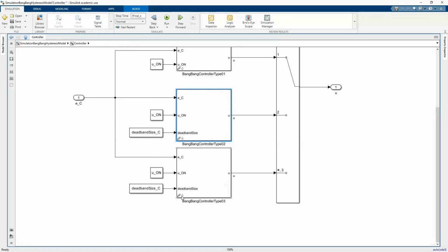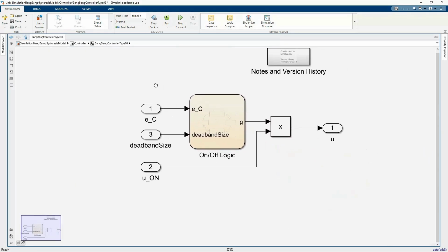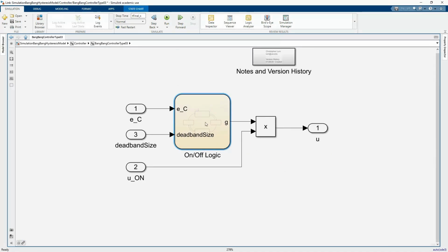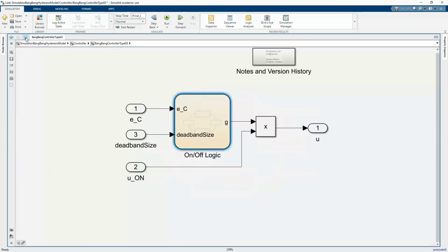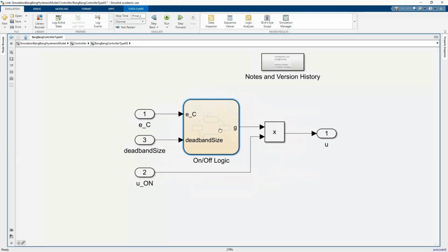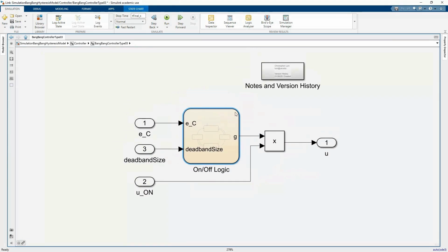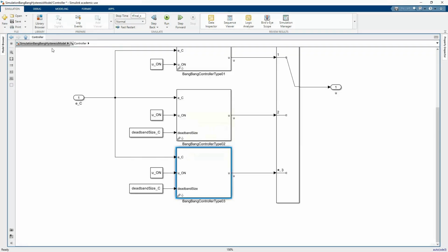And then the other controller is the Stateflow representation, or the finite state machine. So you can see I replaced that logic with basically the picture we drew on the board. And hang around for a little bit. I'm going to run through the simulations first just so we can see the behavior, but then I will show you how to build this from scratch, because I know Stateflow is potentially new to some people. This is another package within Simulink that's going to allow us to build these finite state machines nice and clean. You can even see it's drawn differently, with these rounded edges. It's called a chart. But again, I just wanted to point out that theoretically these two are the same thing. These are both the bang bang controller with the hysteresis deadband.